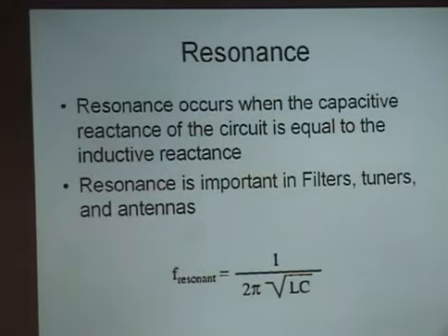Because normally it would come out to a 50 ohm SO239. Yeah, SO239 is at 50 ohms. Normally on the inside of that, you have a coil. On the outside of that, if you have a dipole, you in effect have a capacitor. So you have a tuned circuit there, which if you want to do it properly and you feed 50 ohms and you want to have 50 ohm from your antenna, it's resonant. And you have in effect a capacitor.